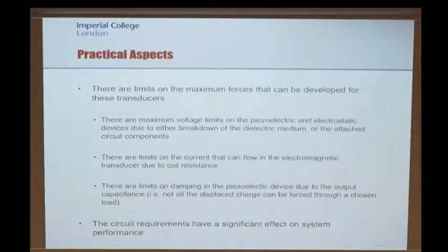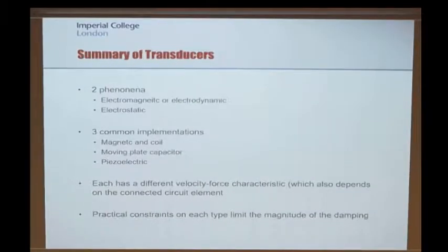Okay, that's basically what I've said here. There will of course be other limits. There's a limit on the maximum voltage that the piezo film is going to be able to support. So if you bend it too much, you'll either see the material starting to crack, or you might see it break down because of the electric field strength that you're breaching. And then there's this fundamental limit on how much damping we can achieve with this piezoelectric material.